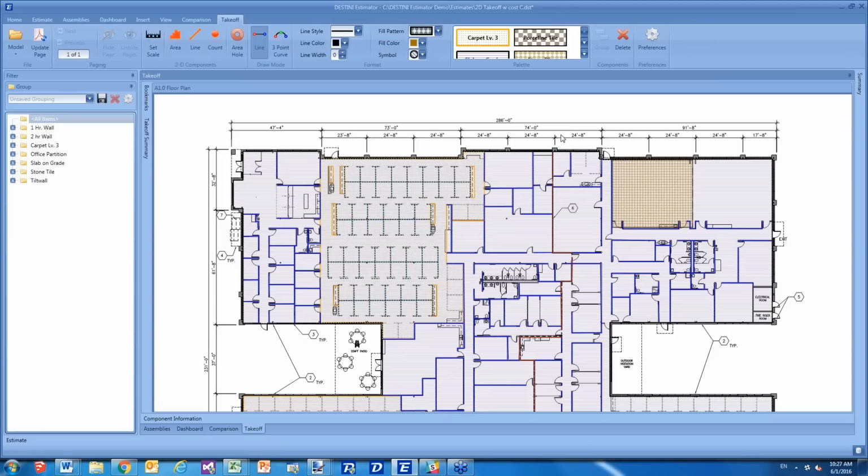All right, I'm going to move over to the 3D quantity takeoff. I'm going to ask a question since it came in. Sure. Before you jump over to 3D, the question is, instead of dragging existing lines, can you add new lines and they will be linked to the selected assembly? Yes, it won't happen automatically though.